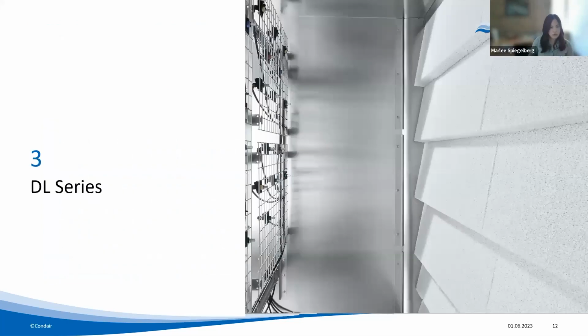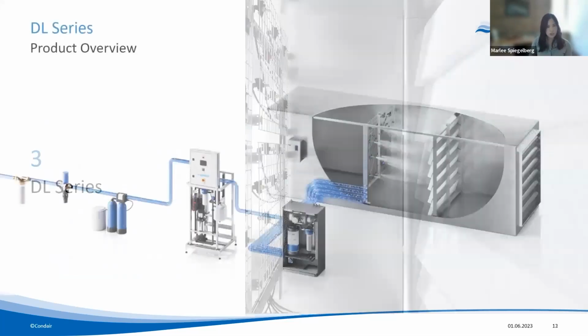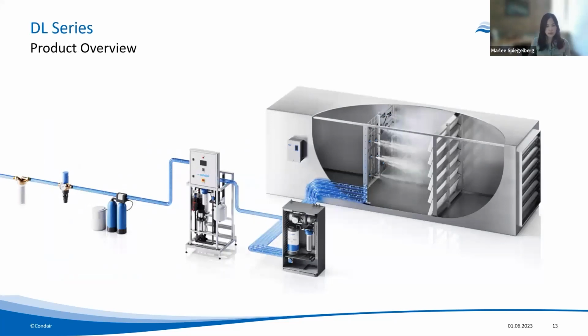So let's do a quick overview of the DL series, and we'll get into the features, benefits and applications. So just a product overview. This is a general DL installation. First we have our filter. This is a pre-treatment for the water treatment that's required. Next, we'll go into a backflow valve. After that, we'll soften. This is a pre-treatment to the RO system. It helps extend the life of the membranes.